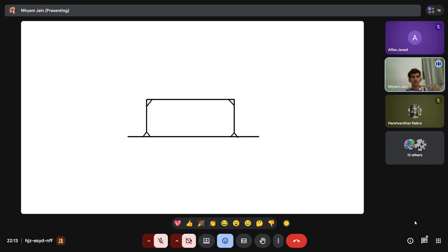And in principle, now the bottom of the wall acts like the pin joint, which I was saying, and the top, because of the corrugations and the connection it will make with the roof, becomes a fixed joint. So now, as a system, it's stable because there are only two pin joints, and there is no rotation allowed.